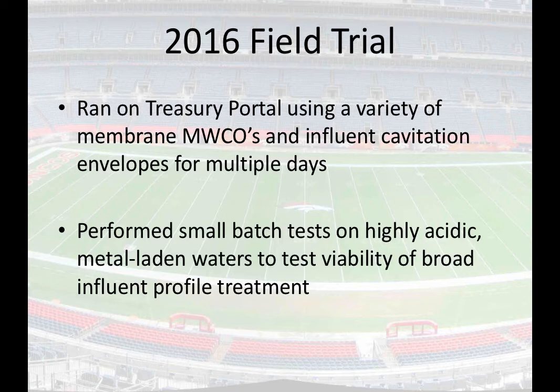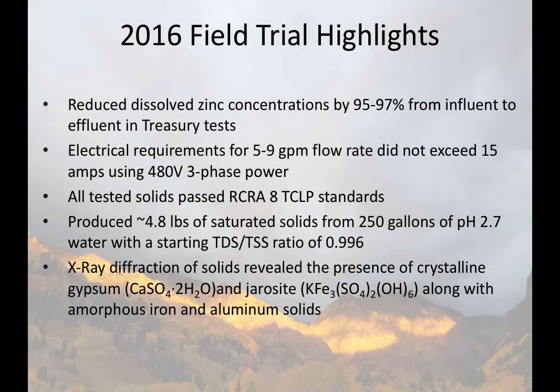And so with this particular system, the goal was, maybe this is it. Maybe we can use something like this. And it performed pretty darn well. It's potentially a piece of the puzzle, but it removed, I think, 98% of our iron, from a few hundred milligrams per liter down to 10 to 15, and 99.5% zinc removal. I'll get into a few of those numbers in a minute. But it did have the capacity to work on a broad influent array, which is really pretty interesting.